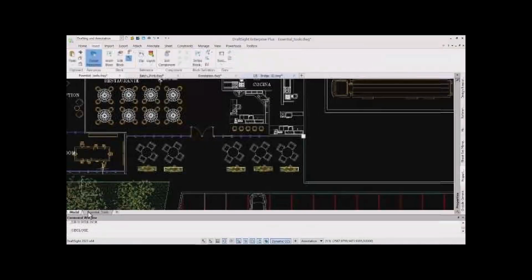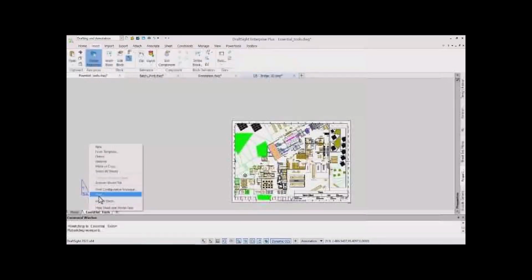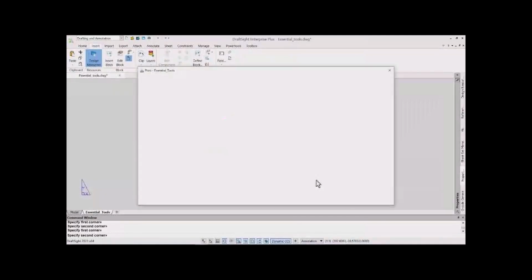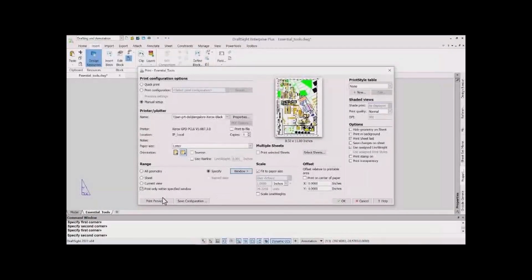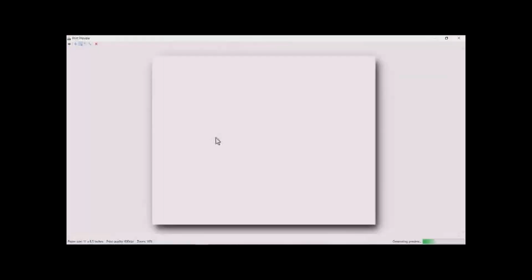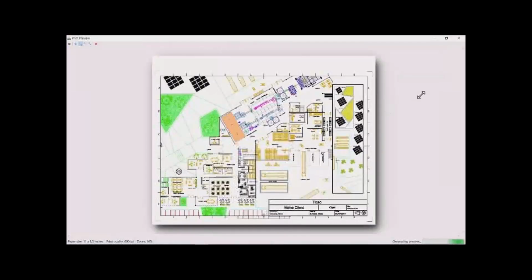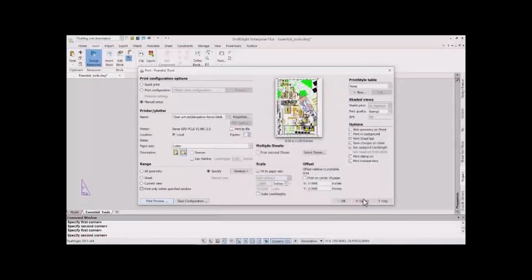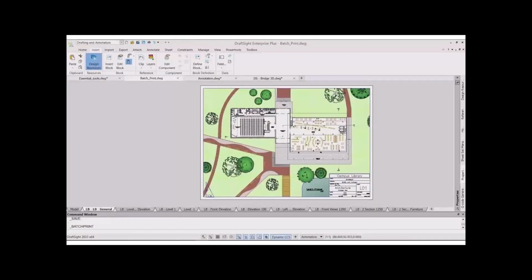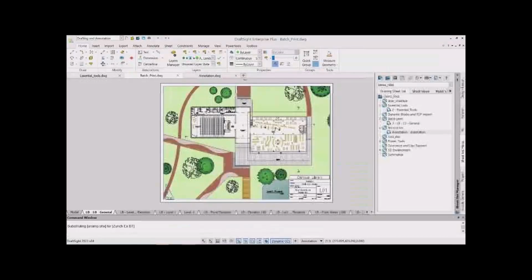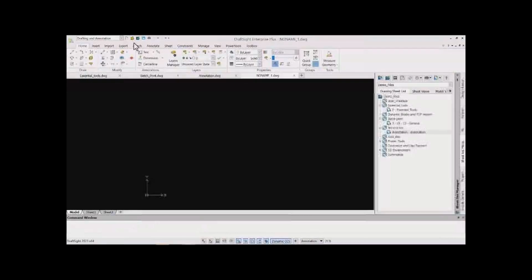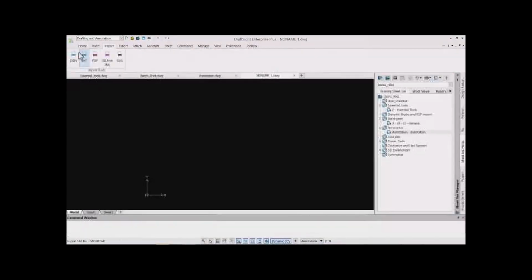And next, once the drawing is created, you can easily print it by applying appropriate settings or batch print. Such files include a lot of sheets in them with different configurations as needed. So when we use this batch print option, we can get the final output here, like the PDF, a high quality PDF.